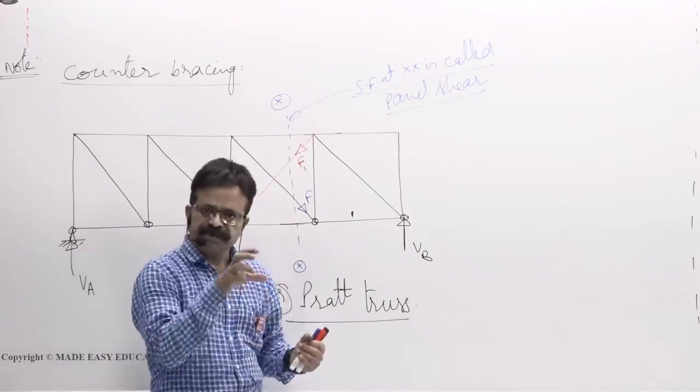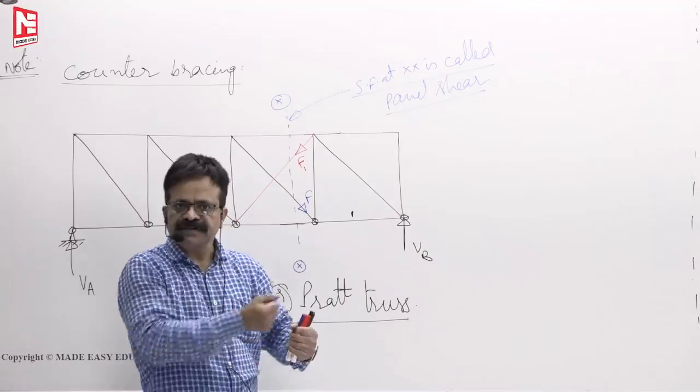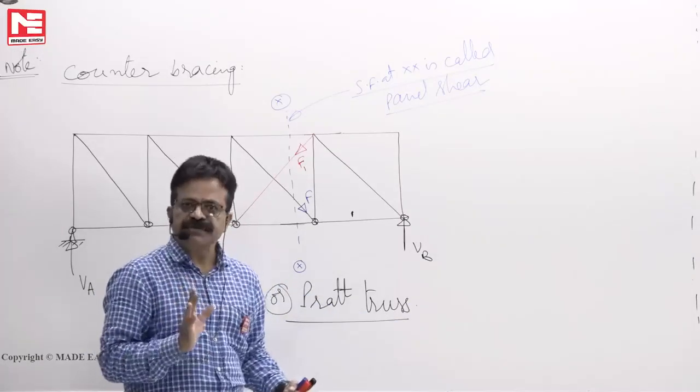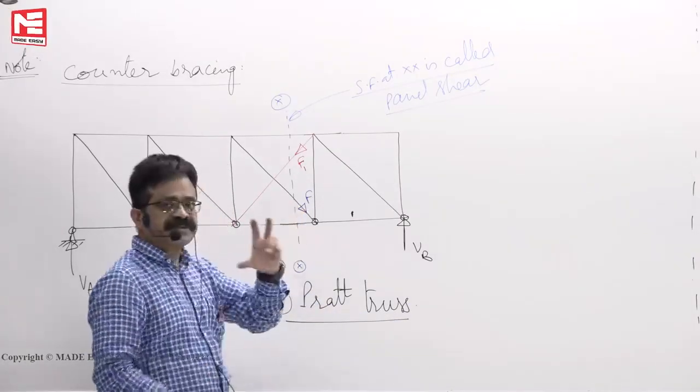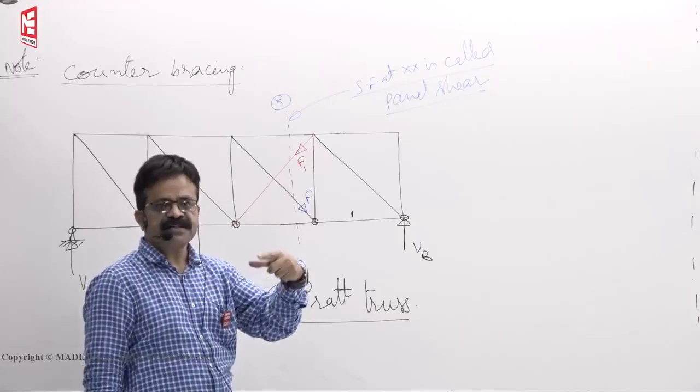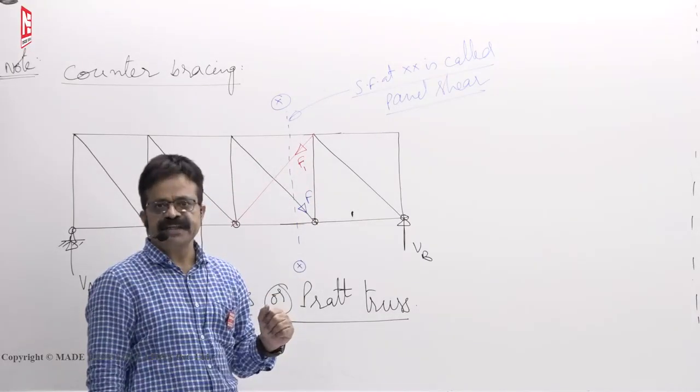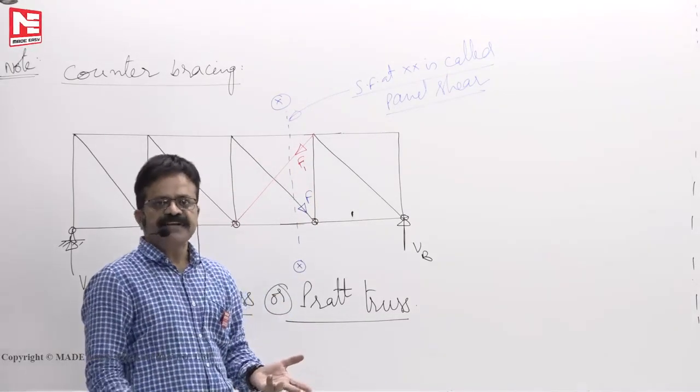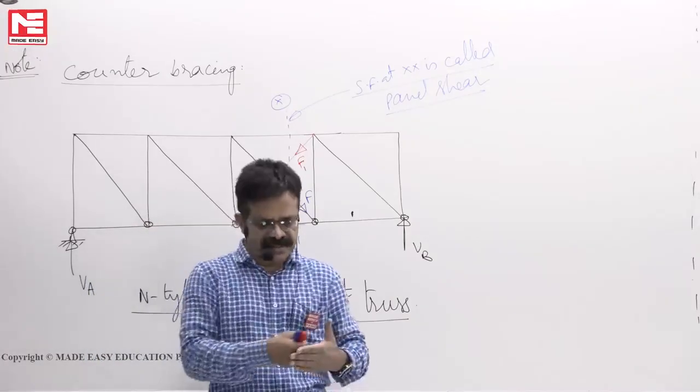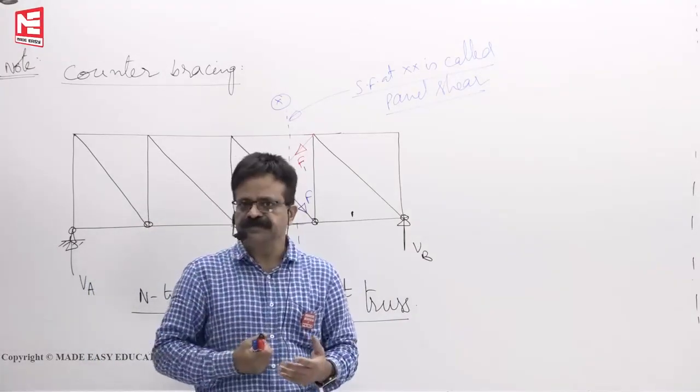If there is a compressive force, there is a tendency to buckle. If there is a tension, no question of buckling. Compared with compression capability, if the cross sections are same, tension members can take at least 2 to 3 times additional force. Why they can take so much high force is the no buckling problem.